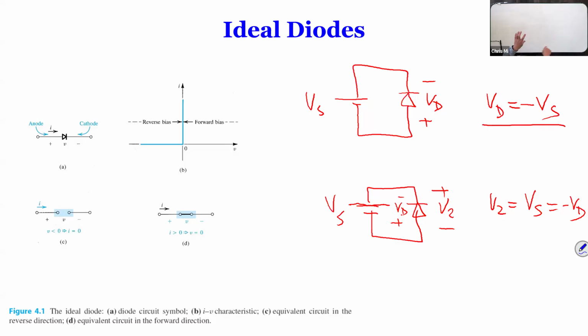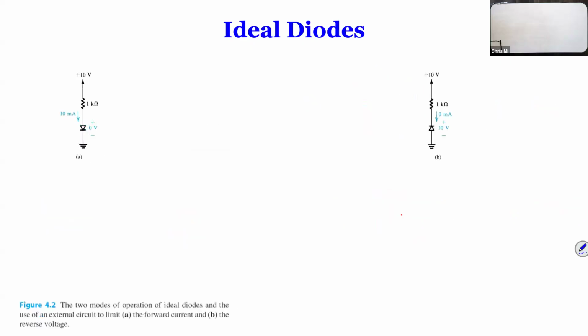When you start to have current going through, the electrons move, the holes move, so the properties change within the material. Now, if you go from positive conduction and suddenly want to move to a negative, blocking voltage, you have to make up reverse charge. That is the current going back to make up the lost electrons to balance, like equilibrium. So that is what it does, okay?